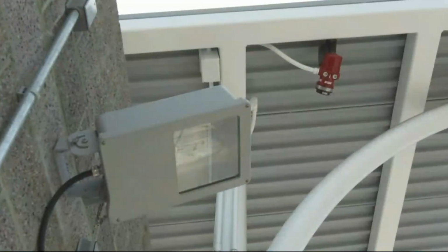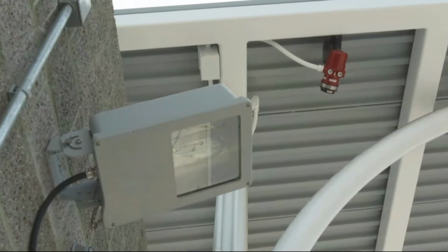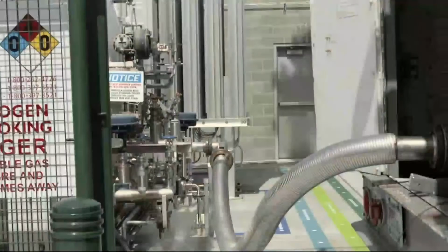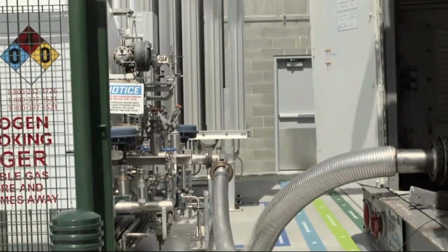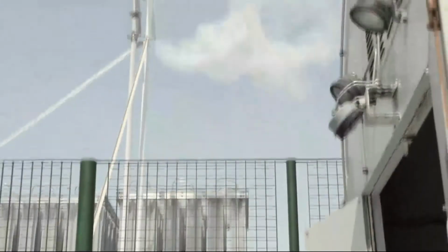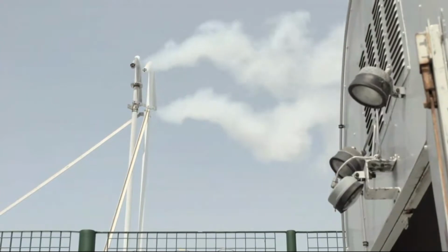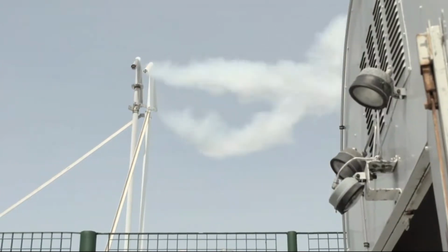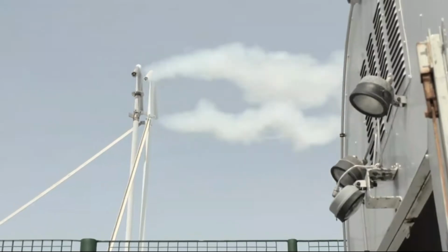Also, all electrical equipment within 25 feet of a hydrogen handling system must be explosion-proof. Safety relief valves on a hydrogen system take advantage of the gas's lightness. They direct the gas into a vent stack, which discharges well above the ground. When hydrogen is vented, it just goes straight up the stack. Unlike some gases, hydrogen is not a problem for the environment.